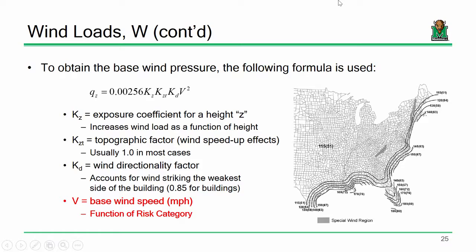Now under seismic, that's a different story, because with seismic you can generate some massive accelerations, and that's a different issue. But we're starting to go down the rabbit hole of the geotech aspects. I would just say in those instances, you're probably just going to have to use deeper piles. Deeper piles are going to generate a larger amount of skin friction to keep the building in place. But I would argue that's more of a concern with seismic than it is with wind.